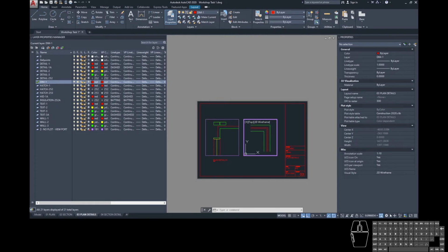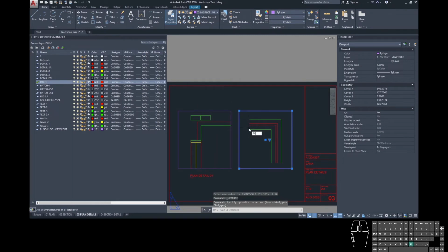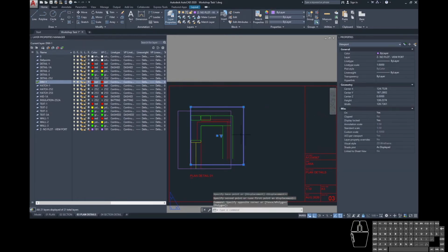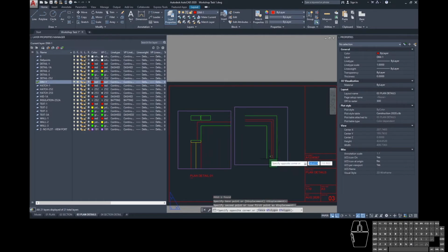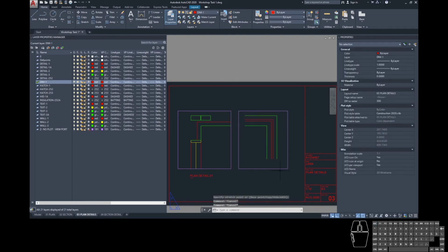which allows us to then activate our new one, unlock it again, and we're going to scroll over, zoom out, reframe back into here, make sure I'm rescaling to 1:10. I'm going to lock that viewport and I'm going to deactivate it. Now this isn't quite sitting where I want it to, so I'm going to use the move tool. You can snap to things within model space from paper space. So to make sure that I'm lining these up right, it's going to nice and neatly, so that all of these lines eventually will, like on the hand drawing one, meet up nice and neat.